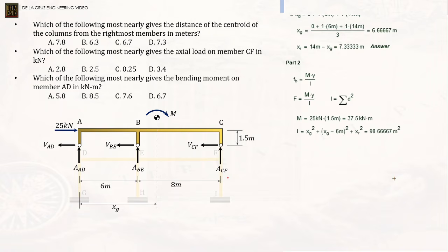By the way, in the cantilever method, the first thing we solve are the axial forces on the columns. Always. Axial forces on the columns. In the portal method, the first thing we solve are the shear forces. Okay? That is what we should remember. So far, what came out in the board exam, from what I see in the CRF, are cantilever method, and there is also portal method, but commonly cantilever method.